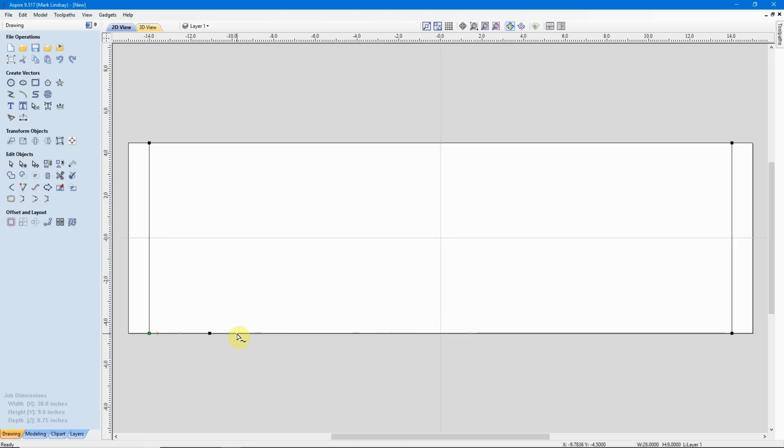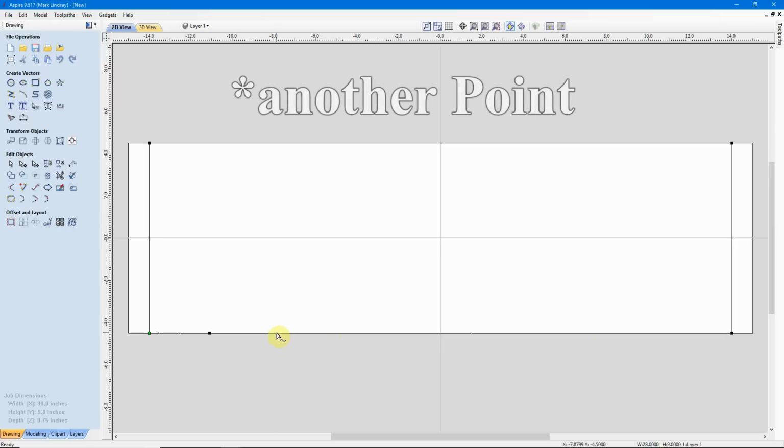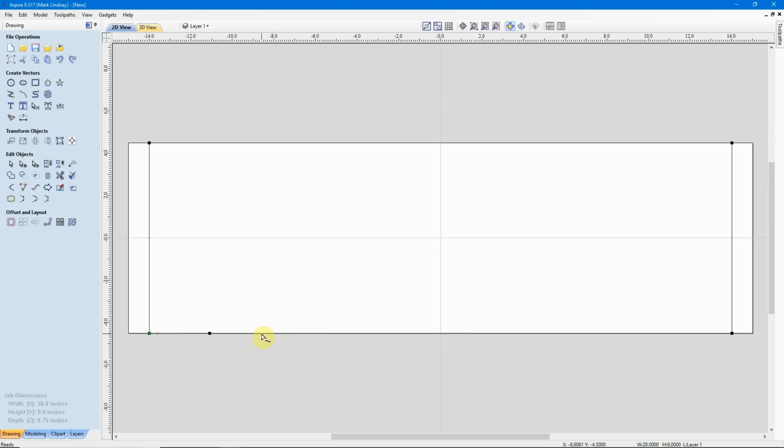To manipulate the vector in a certain direction without changing this shape down here, I want this to stay more or less straight, I'll need another vector. So I'll come over here, put the tip of my cursor over this span of the vector, and remembering that keyboard shortcut, I'll just type the letter I, and it inserts another point there.